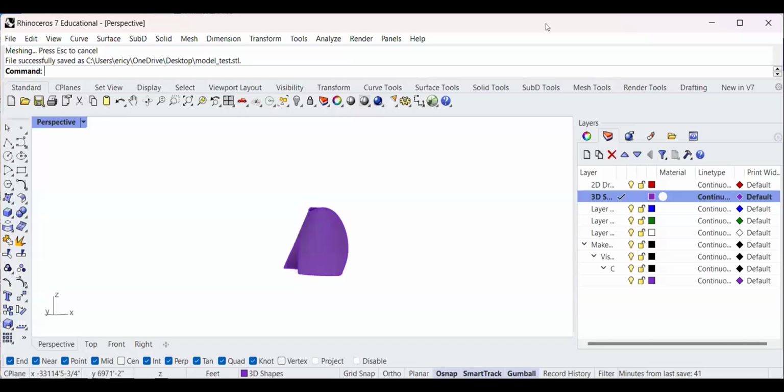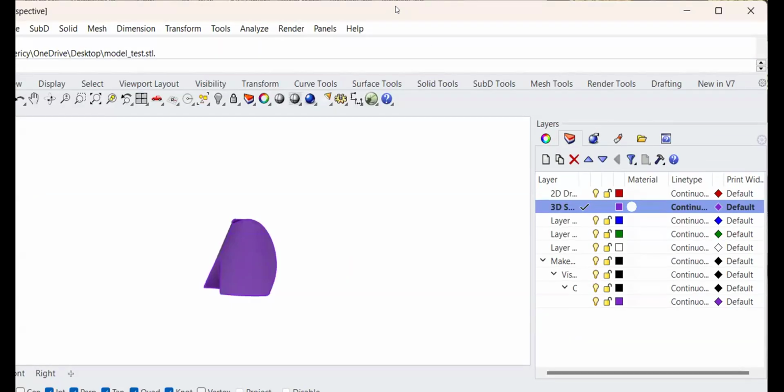And a lot of times I don't need any support systems for this one. Sometimes, again, gravity is important. And so if you have something that's overhang, you have to have support systems. And on this one, you could just turn on support systems and click on slice and it will slice the print. And oh wow, that's really fast. So it will print this thing for me in 12 minutes. Okay, so that's an option if you want to create some models with a 3D printer.